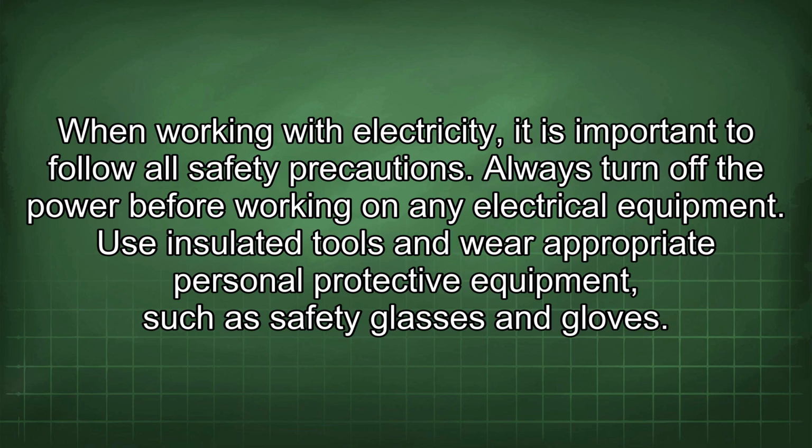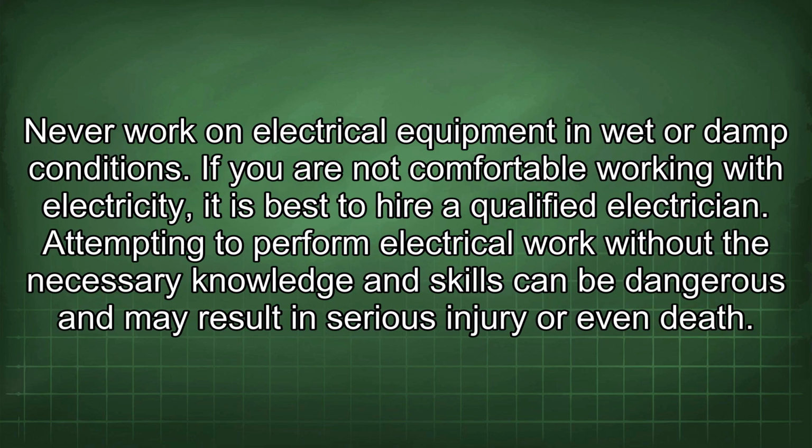When working with electricity, it is important to follow all safety precautions. Always turn off the power before working on any electrical equipment. Use insulated tools and wear appropriate personal protective equipment, such as safety glasses and gloves. Never work on electrical equipment in wet or damp conditions. If you are not comfortable working with electricity, it is best to hire a qualified electrician. Attempting to perform electrical work without the necessary knowledge and skills can be dangerous and may result in serious injury or even death.